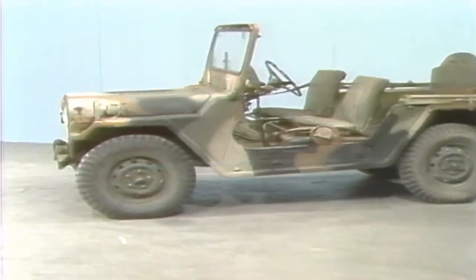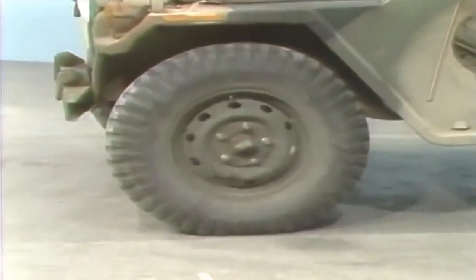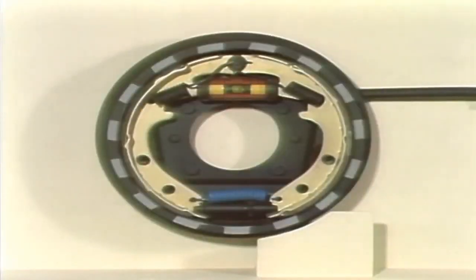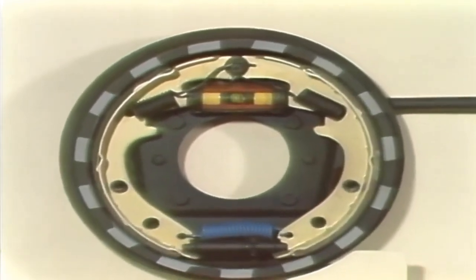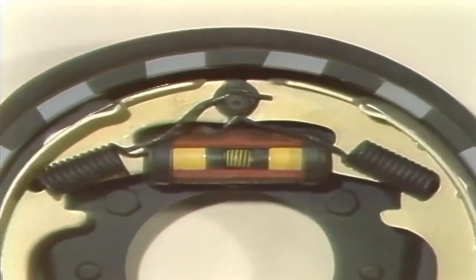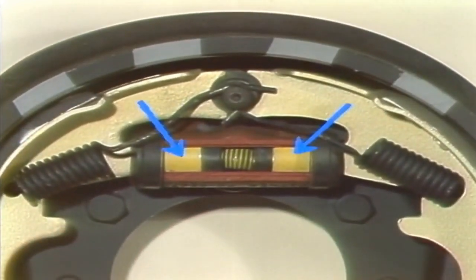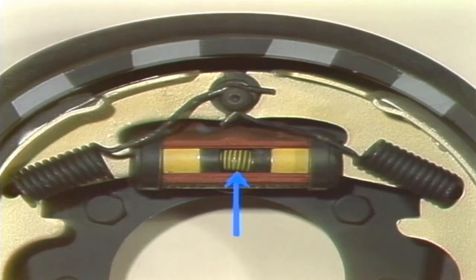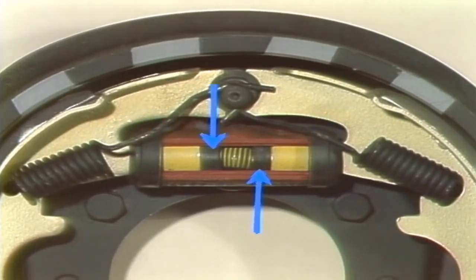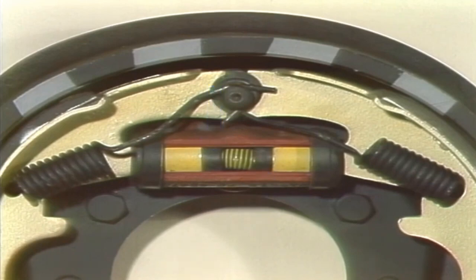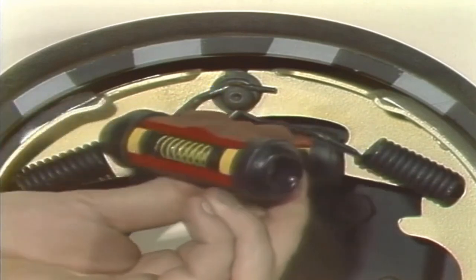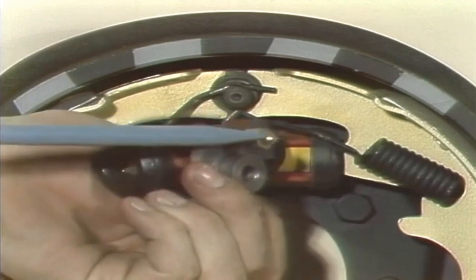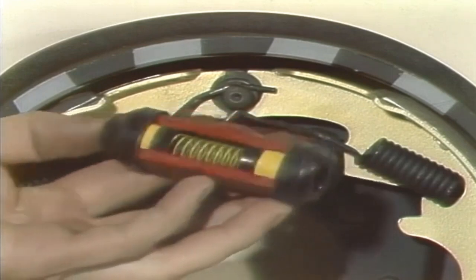Now let's get into the other active hydraulic component, the wheel cylinder, and see how that operates. This device is connected to the steel brake lines by a flexible tube that allows for up and down movement of the wheel. Inside are two pistons that bear on the brake shoes, a spring that positions sealing cups against the pistons, and a bleed air valve that lets you get rid of air in the brake system, as we're showing you here on another wheel cylinder.